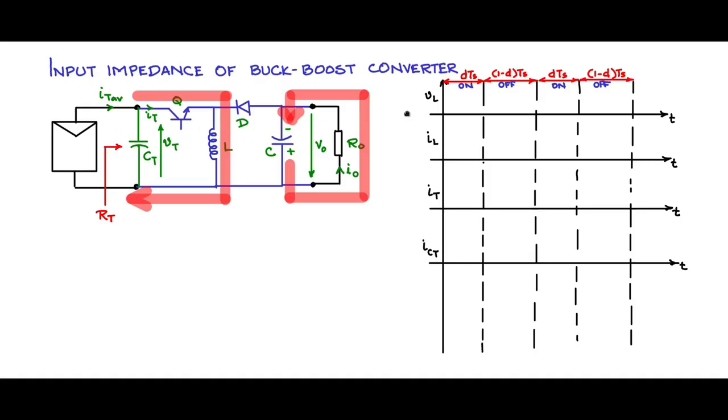Let us now write down the waveform during this period. So let us first look at the voltage across L. We will mark this VL with the polarity of measurement in this fashion. The common point of the probe is kept in this terminal, and the measuring point is kept on this side, as indicated by the arrow.